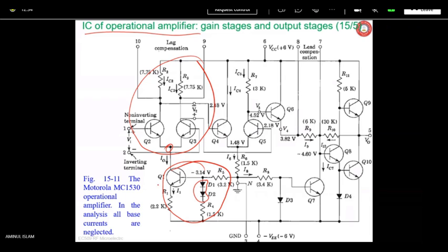That is 5.2 kilo ohm. Here also another one. That is from here. 5.2 kilo ohm. If you consider this, and also you are doing the AC analysis, so VCC is grounded. Remember, this thing is not shown, but for AC analysis you have to understand that. So actually 5.2K and the R2, R3, that is the collector resistance of Q2, Q3 are coming in parallel,